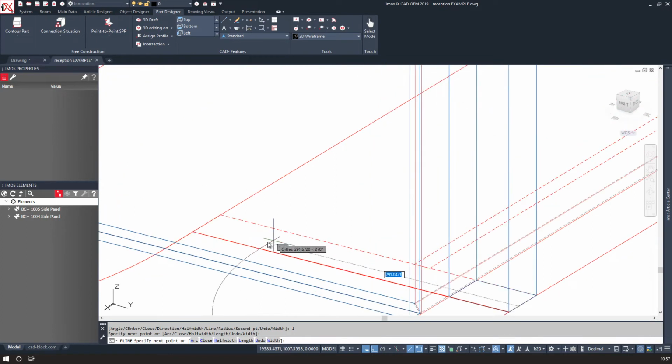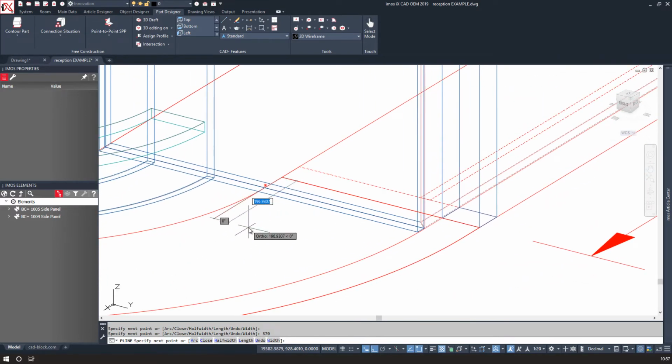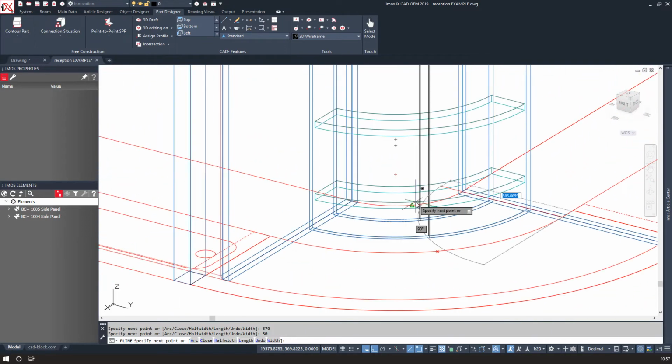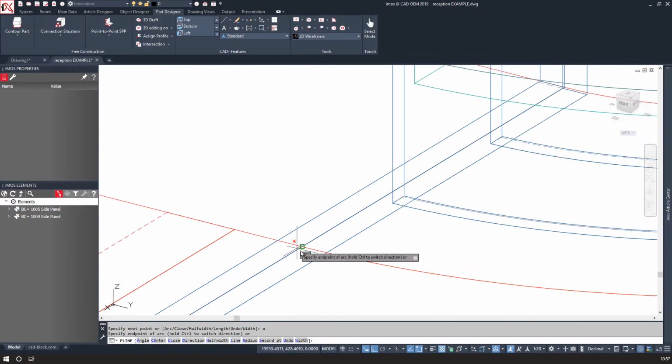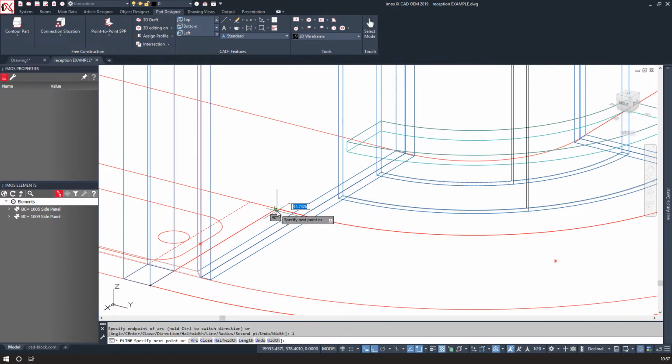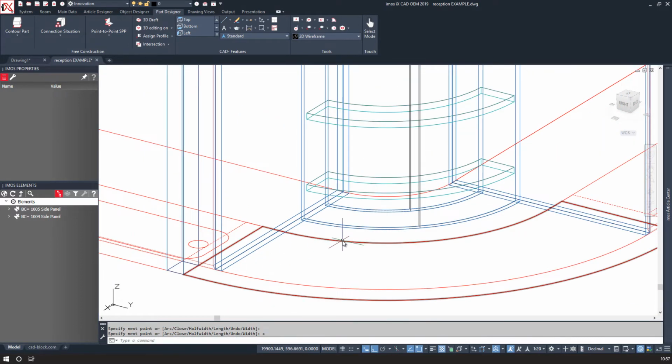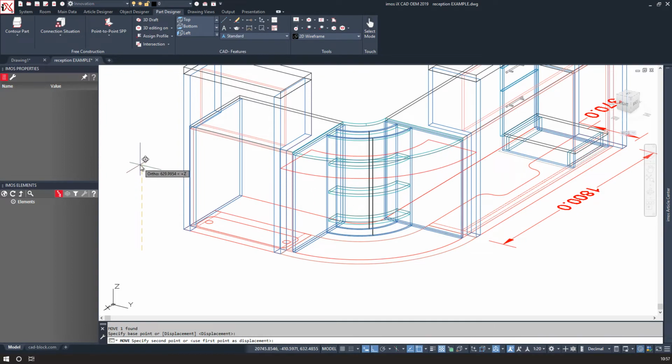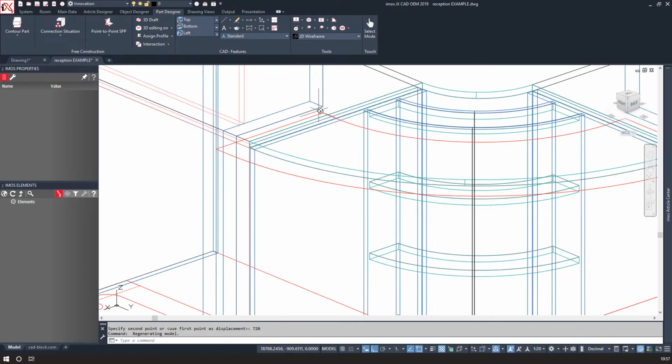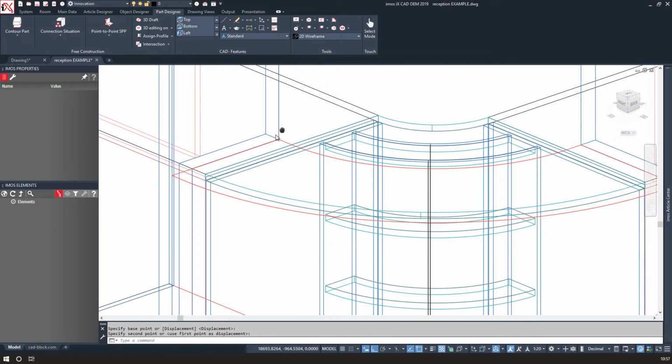We'll make some decorative worktop, I think this is, or some sort of addition to the existing worktop to make it look like the thicker material is running all the way around. So I'll use the same tool as before, the polyline tool, and I can switch between line and arc segments within the polyline by using L and A and pressing enter in between, and then C to close it. And I'll just move this up so that it's in exactly the correct position.